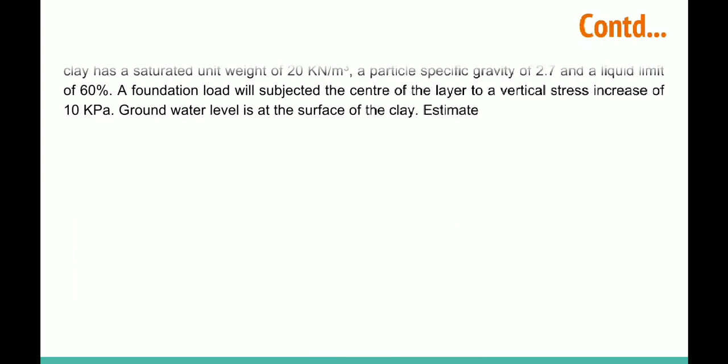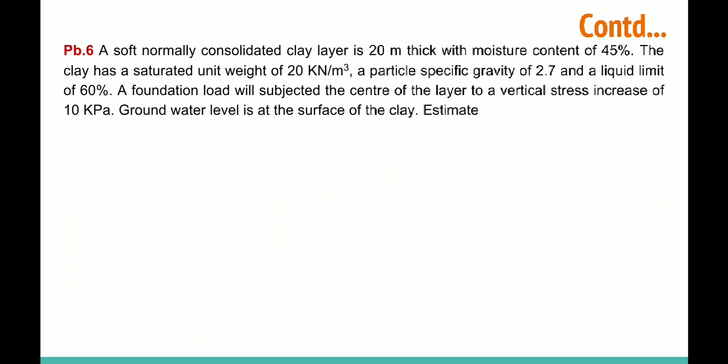So the next question we have: a soft normally consolidated clay layer is 20 meter thick with moisture content 45%. The clay has a saturated unit weight of 20 kN per meter cube, a particle specific gravity of 2.7 and a liquid limit of 60%.